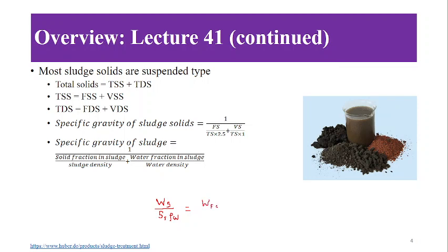weight of fixed solids upon specific gravity of fixed solids into density of water, plus weight of volatile solids upon specific gravity of volatile solids into density of water.